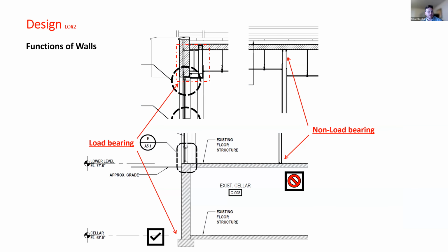In this view, please note the structural column in alignment with the roof above, the floor below, and the proximity to the exterior wall, providing lateral stability to the building envelope. This is a load-bearing wall condition. Then we can see the non-load-bearing condition and the partition to the right. That carries no weight other than its own.